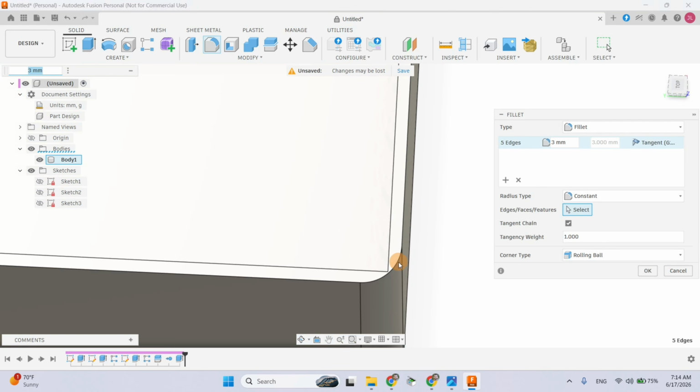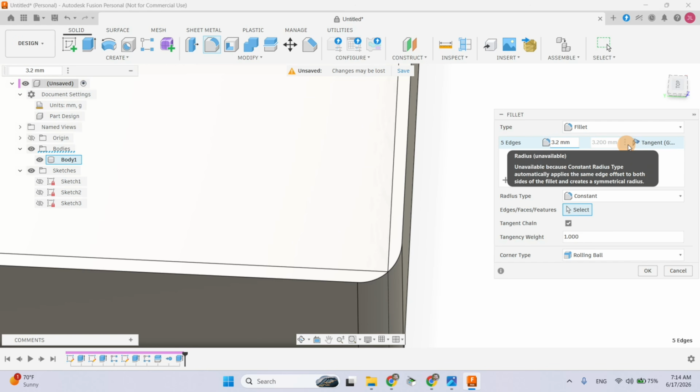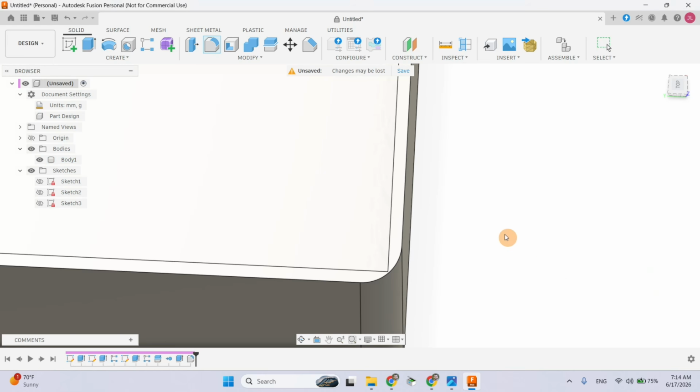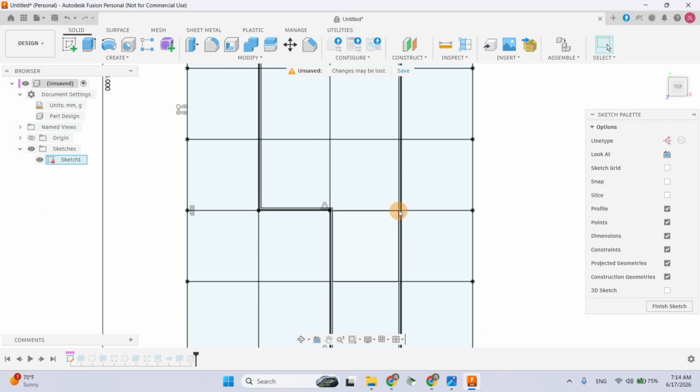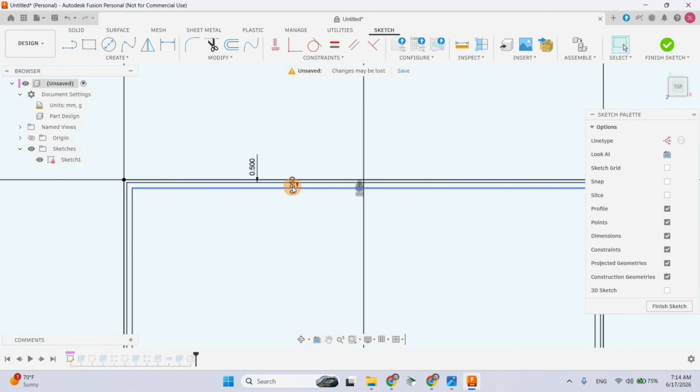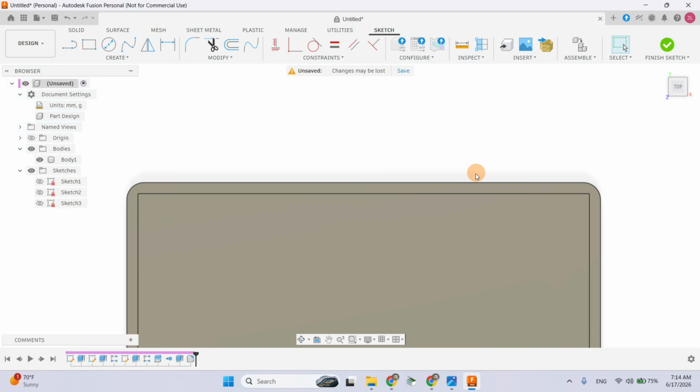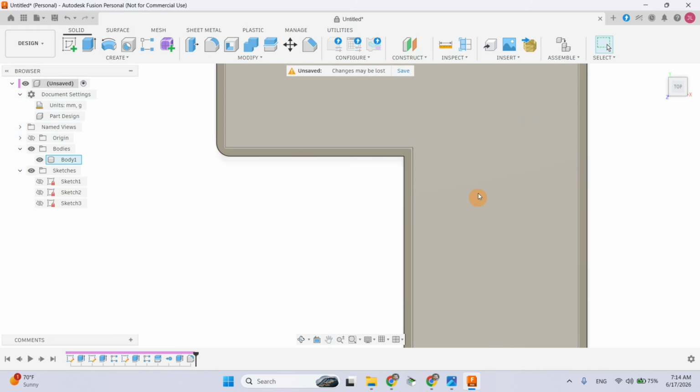Our wall thickness is actually too skinny right here, and so you can see if we make this bigger, it starts to cut off to a point that eventually there's just going to be no material there. So let's leave this 3 for now, and let's actually make our wall thickness bigger. If I come back into our first sketch, select this offset here. Yeah, we can make this thicker. Let's do 1.95. So why not? We've got plenty of space for those knives in there.